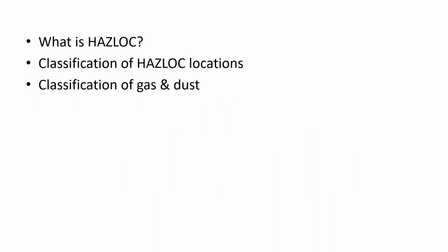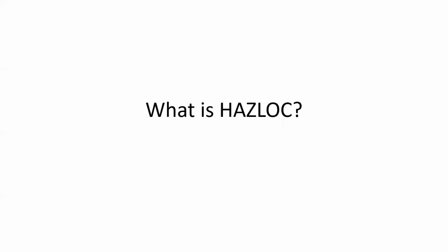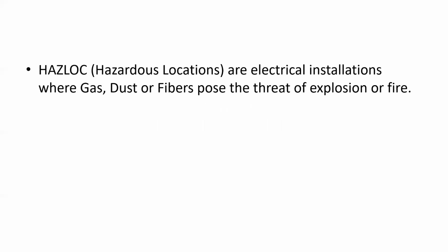In this presentation, we're going to be looking at what is HazLoc, the classification of HazLoc locations, and the classification of gas and dust within HazLoc. HazLoc is really shorthand for hazardous locations, and these are electrical installations where gas, dust, or fibers pose the threat of explosion or fire. They come in many different forms.